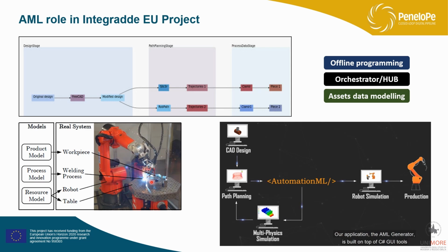part. So there are many software tools involved in this tool chain, and we have the CAD design of the parts, so the geometry of the part to be realized. We have the elaboration of the deposition paths. We need to simulate the geometry, the behavior of the part, of the metal being deposited, and the distortions, and possibly update the geometry or the path planning.